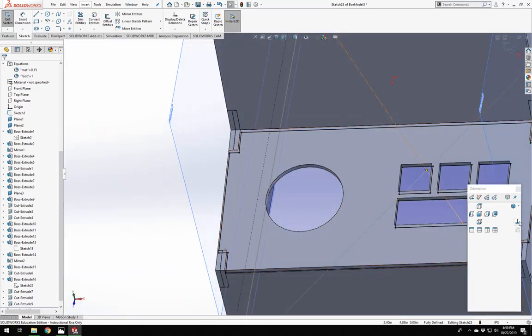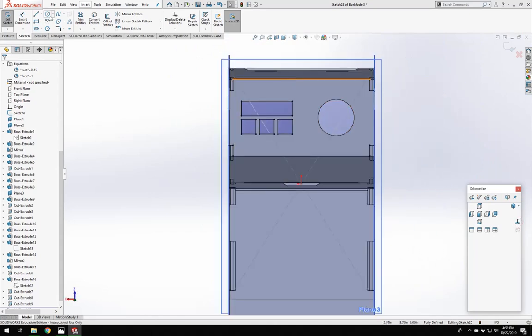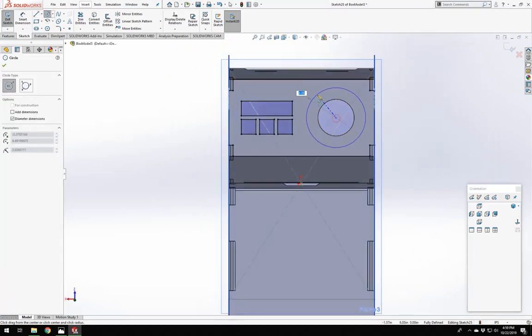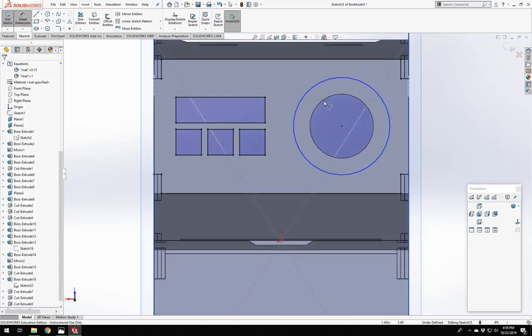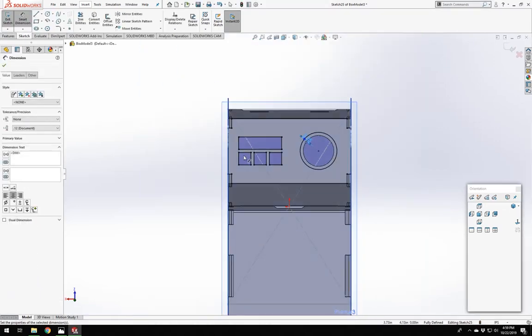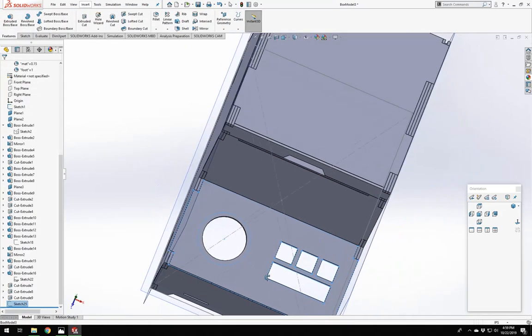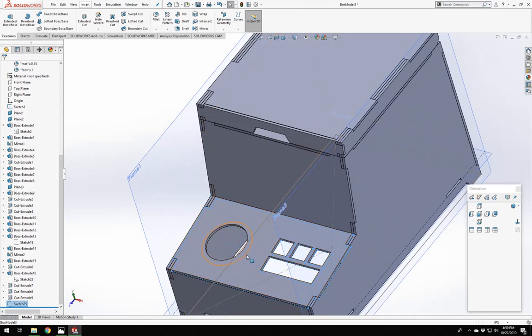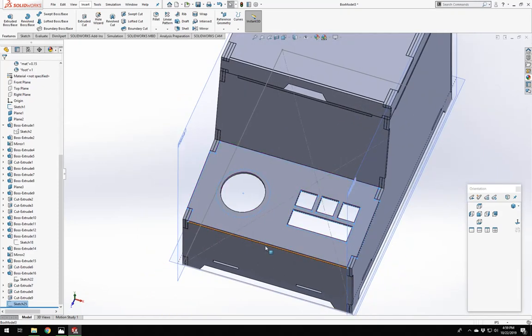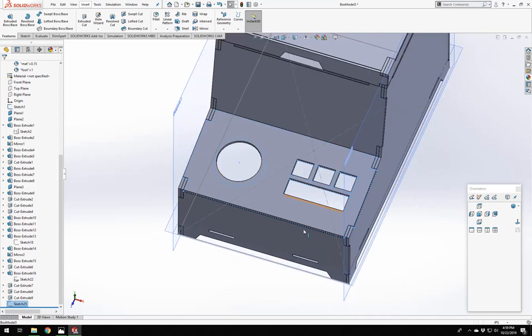And then our knob, though, has to be done slightly differently on this layer. So what we're going to do is make a larger circle that is some level of offset, maybe 0.25. So what's going to happen is when we laser cut this out, we'll end up with this larger circle. The bottom layer that we're going to do shortly is going to be completely solid. And so when we assemble this, we'll end up trapping that larger circle within this space and then sticking our knob to this surface. And so as a result, the whole thing will be able to rotate. It'll be a trapped rotating part.